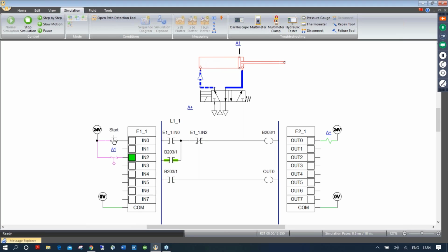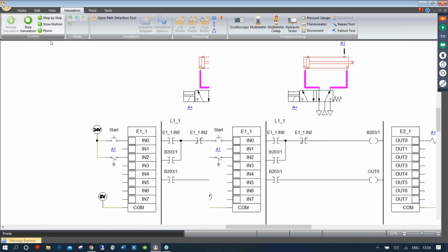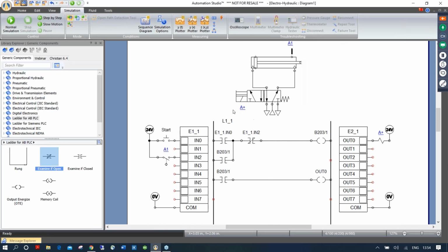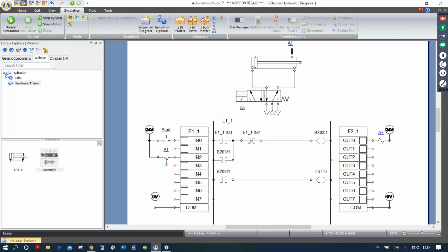But if you don't want the students to have to go on the pressure source, change it, and reduce its diameter, well, keep in mind, like we said before, you go in your library, you can create a main category called, let's say in this case, pneumatic, and you can drag this pressure source in your library. So next time a student does a schematic using your library, it will simulate right away at the speed that you want.